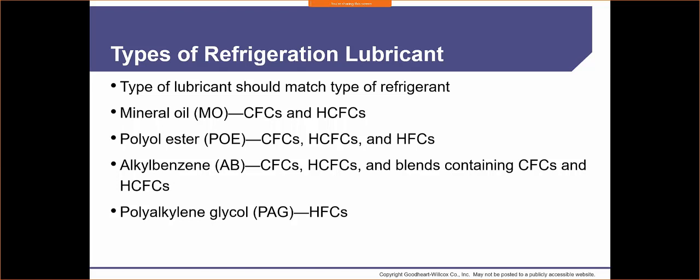Basically, the flush sends a chemical agent through which scrubs the sidewalls of the copper tubing and cleans all the gunk out of the system. The problem is if it's not done properly, that flush stays in the tubing. You seal up the unit, and all of a sudden the flush is inside there, gets run around, and it actually destroys your system because it's not supposed to be in there.